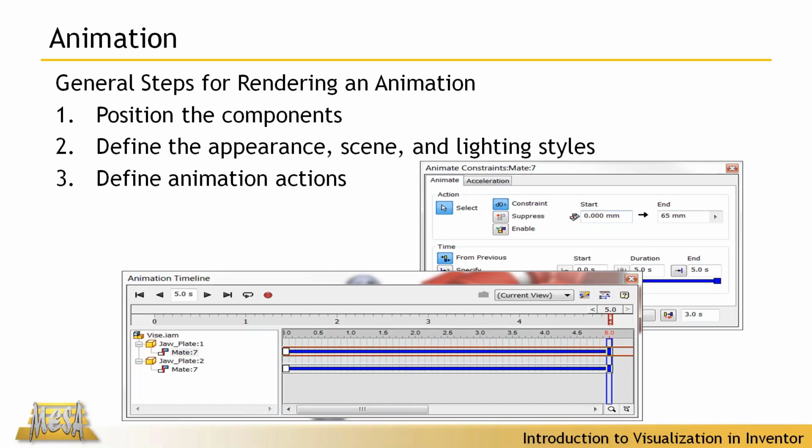However, in the first 2, at least in the case of the constraint, you have to have it constrained using the right constraint that you can control that offset for. In the case of the component, you really don't have to worry about that, but then you do have to suppress it. So there's definitely some differences there, some pros and cons of each type.